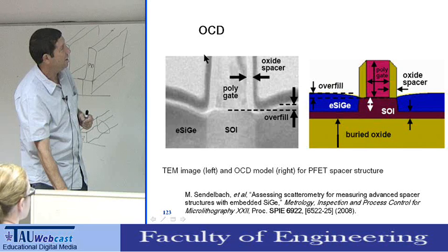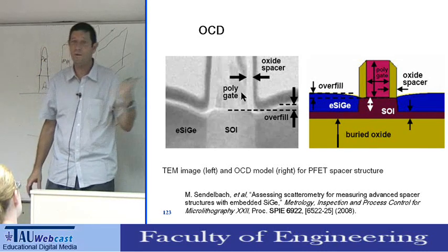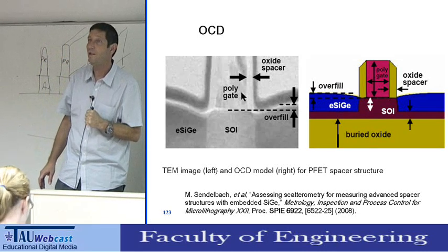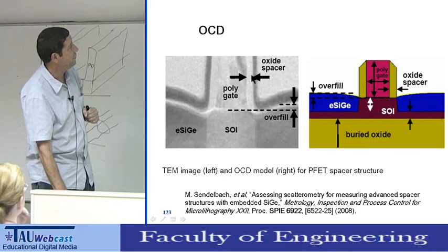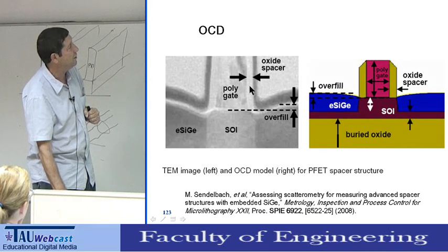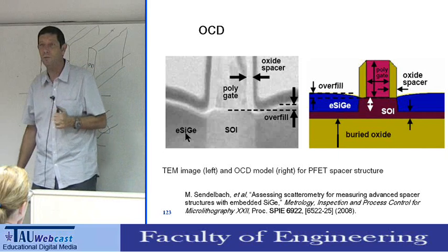This is a polysilicon gate. This material is called polysilicon, and we will discuss it in the lecture on chemical vapor deposition. We will discuss how we make this polycrystalline silicon. After lithography, this photoresist is very, very narrow. Typically, on the side of the photoresist, people put a spacer in oxide, this white stuff. Under it, we have SOI, silicon on insulator, and the source drain here is silicon germanium. This is very advanced 32 nanometer technology.